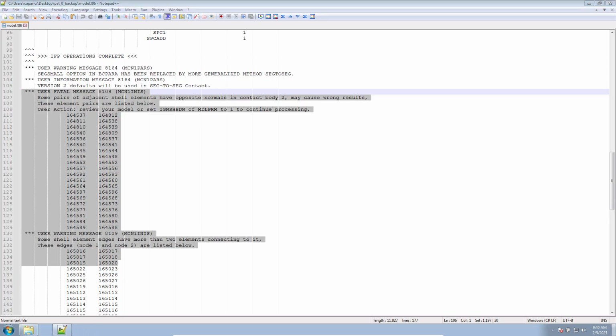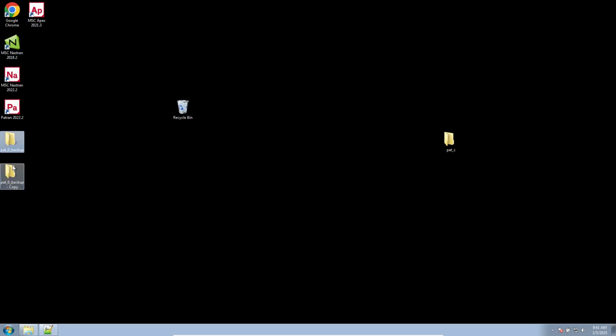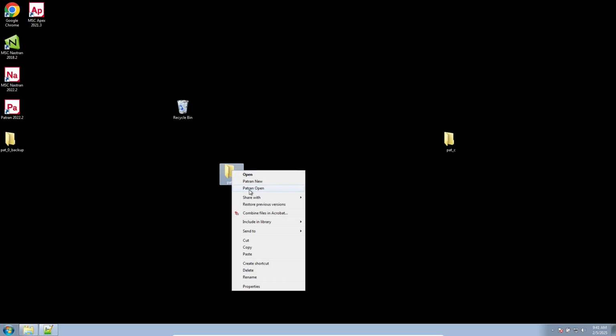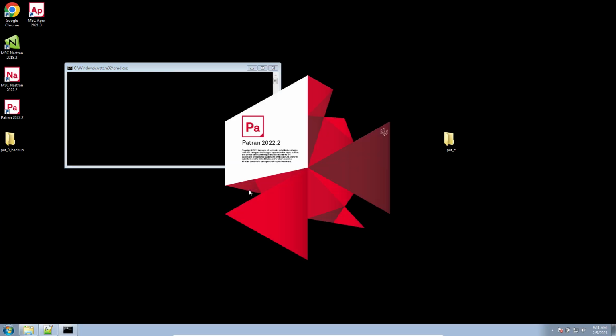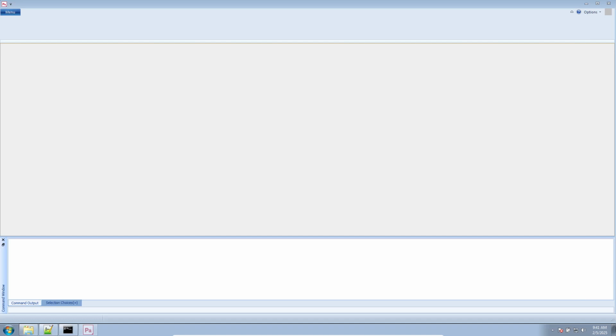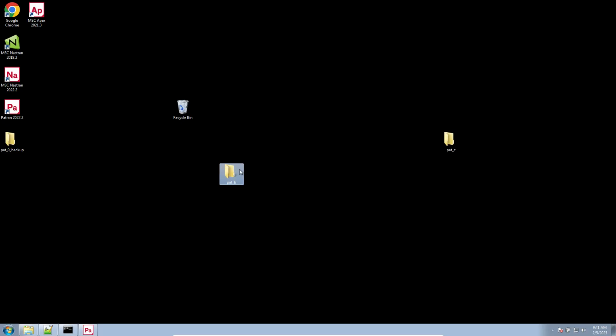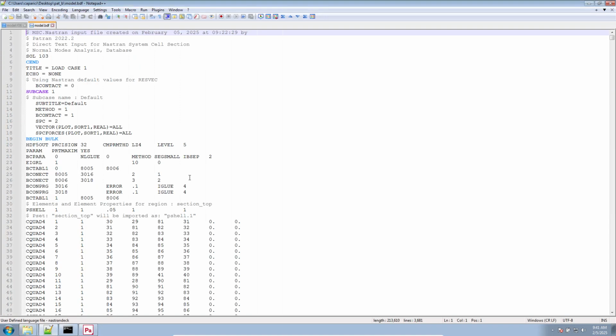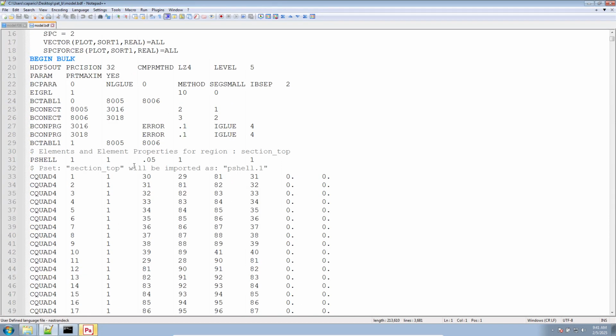Let's go ahead and close this window, and let me make a backup of this original database. So let's go ahead and start. Now, there is an element normal that I have to define. So an element normal for 2D is as follows. When you look at the 2D element, for the most part, when you're looking at a CQUAD4, it's composed of 4 nodes. You use this order of the nodes to determine the orientation of the element.